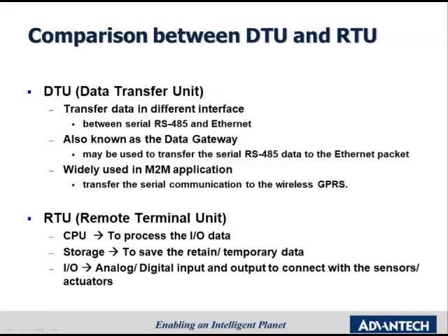The RTU, on the other hand, is short for remote terminal unit. Unlike DTU, which only transfers the data between different interfaces, RTU has the ability to process and store data inside it for different kinds of application scenarios. The RTU usually is composed of the following components for the different functionalities.